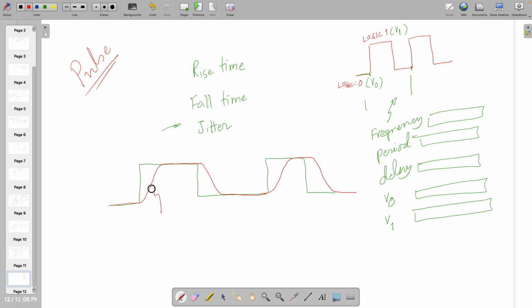So you need to define the rise time and fall time. If you have not gone through these terms, I recommend that it was part of IC 160. Please go through it, it's very simple. It's the time going from 0 to 90%, and the other one is in the reverse way, the fall time.